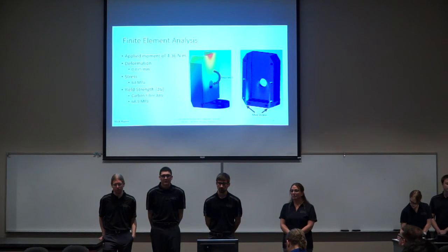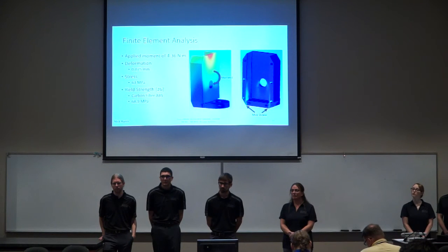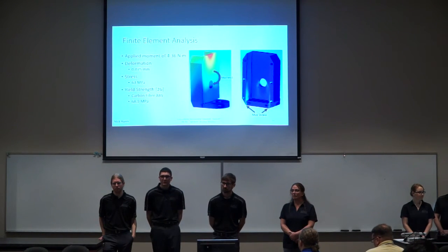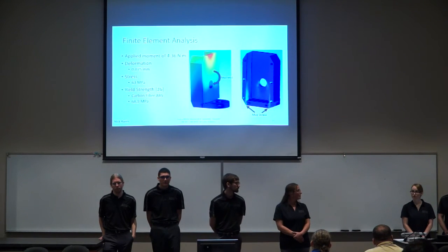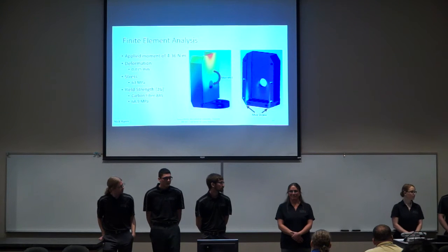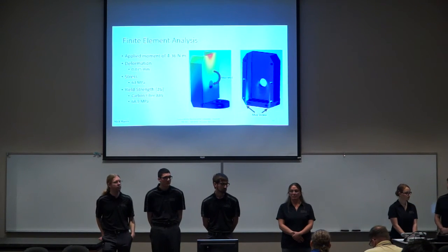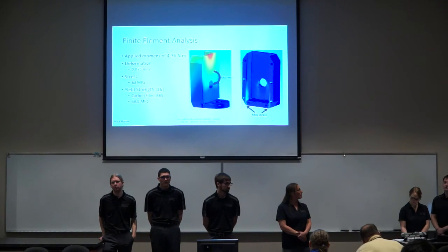Slide 34, this is your finite element, and it looks like you're well within any requirements. But I was just going to ask, it looks like that's a static analysis based on the payload and the moment arm. Is that how you determine the applied moment and the applied loads? The moment was based off of the torque in our torque calculations. That's just the maximum torque that we're going to achieve when we're holding our maximum load.